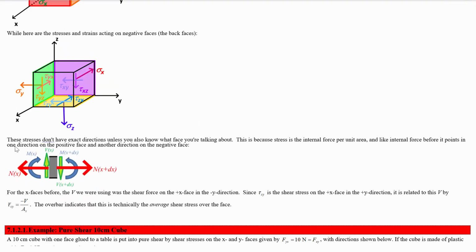So this is always going to be true because they're internal forces, right? When you're talking about the positive x face, you have a direction for the force that you've assigned, and that's the same as the force on the opposite face in the opposite direction at any point. So if you just say sigma x is positive and someone asks, okay, what way does that point? You say, well, on what face? On the positive face, it points in the positive direction.